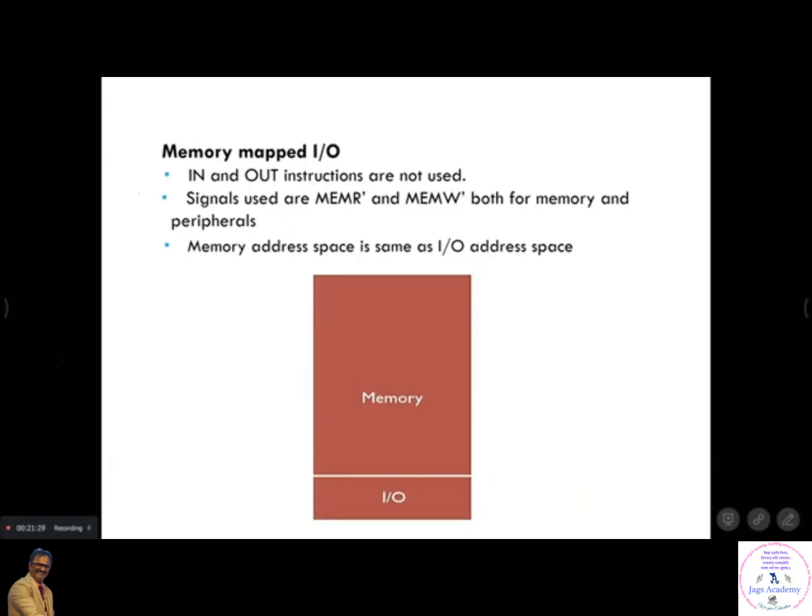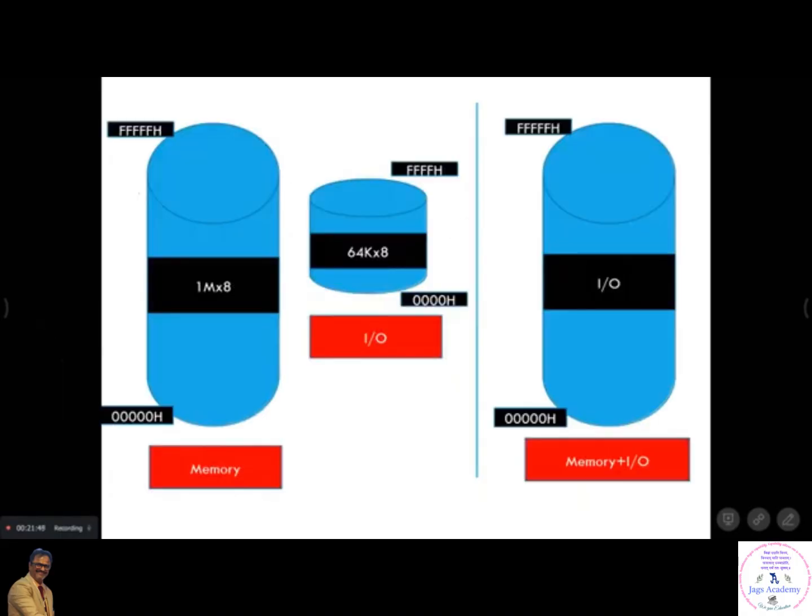That means whatever memory location you have here has the data from IO devices. Whenever the microprocessor wants the data from that IO device, it will look into this memory location. Have you understood this now? Yes or no? Okay, let us go forward. So these are the memory mapped, memory plus IO mapping. These are the memory divisions.